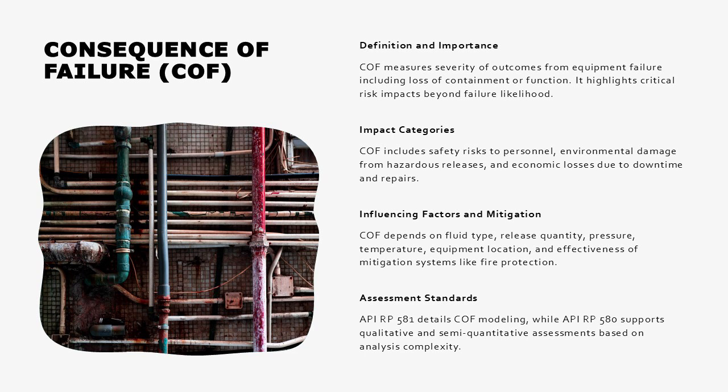Consequence of failure, COF, describes the severity of outcomes that may result if equipment fails and experiences a loss of containment or functional integrity. In API RBI methodologies, COF typically considers multiple impact categories, including safety and health impacts to personnel, environmental damage, and economic or business-related losses.